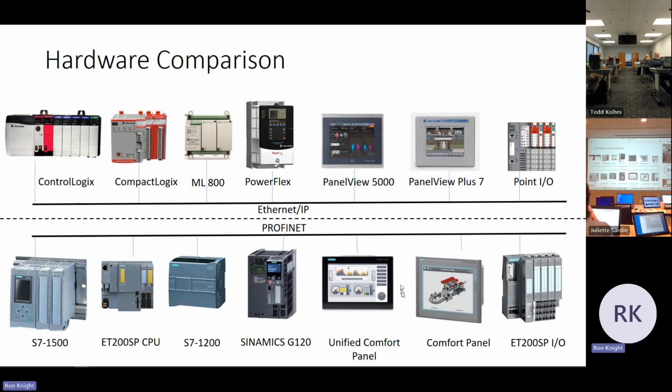The comfort panel, again, not a fair comparison. Comfort panel, you've got very strong VB scripting. Again, out of the box, you can talk to a lot of different PLC brands. You don't have to worry about third-party licensing or third-party OPC servers. Just a very capable HMI.